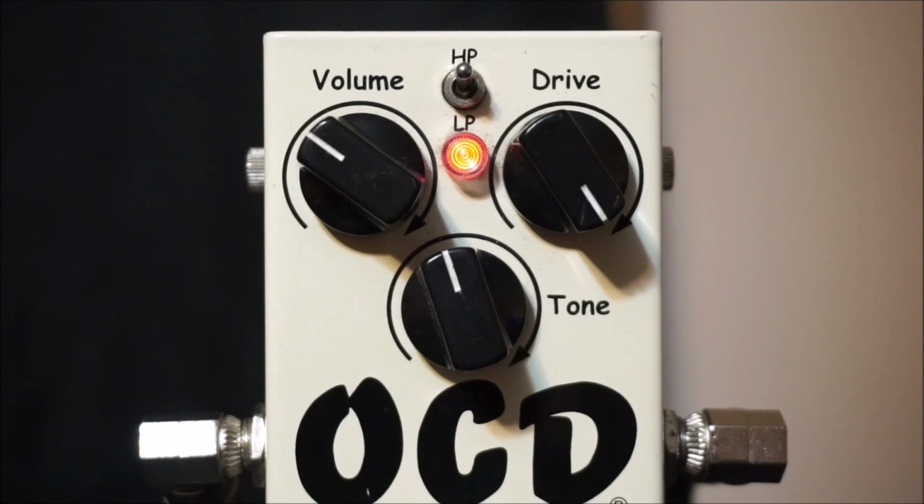But we don't live in an ideal world, and as it were, for preamplifiers and a lot of our effects units, they are designed to intentionally not allow that much amplification, or at least clean amplification, whether we're talking about the tube gain stages in a 2203, or the clipping diodes in a Tube Screamer, or the multiple transistor gain stages in a fuzz pedal. What we ultimately hear is a circuit running out of headroom.